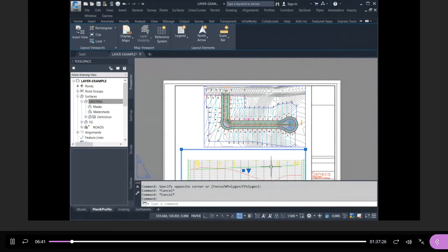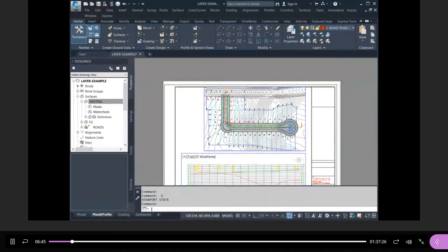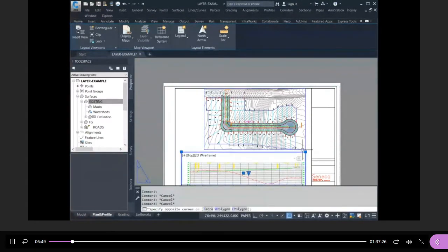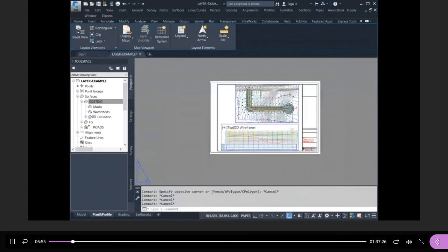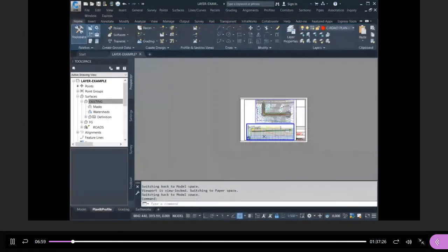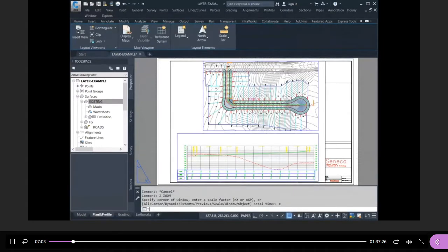and you turn the lock off and you go in there, when you zoom, you're going to screw up the scale. So to prevent that, what we do is we take both frames and we lock them both. And now if you go into the view window, when you zoom, it actually zooms paper space, not model space. Okay, so make sure you do that. So that's the first thing.